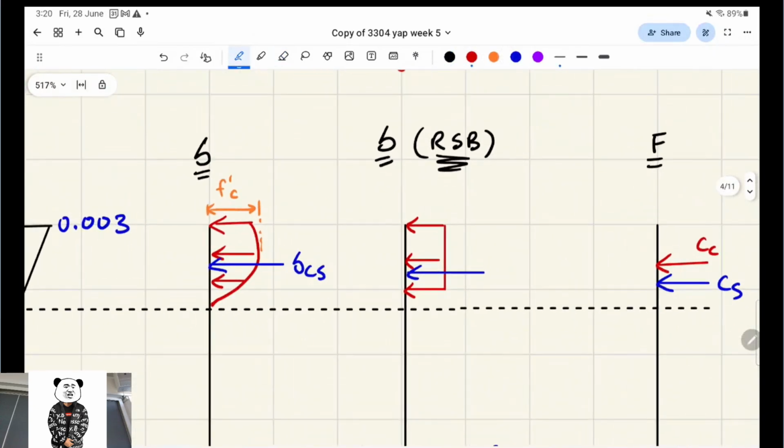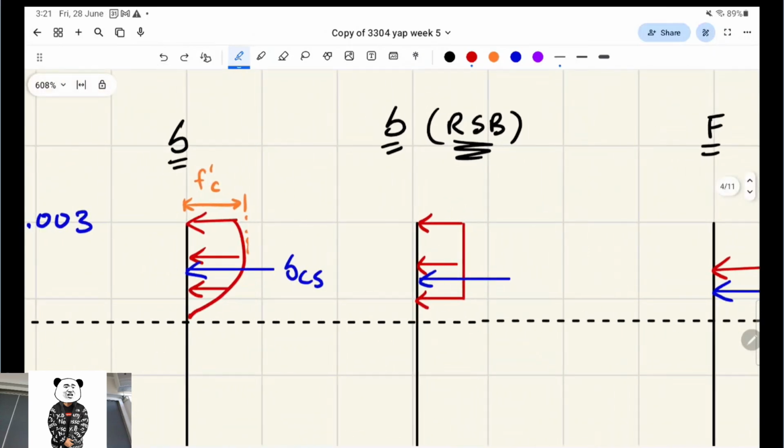And you can see, based on how we can transform this shape, it's going to be a bit shorter, so it doesn't fully reach the neutral axis. We don't really consider any of that concrete in compression using this method, because we're trying to find the resultant force later, which is in the middle of a rectangular distributed load, right?